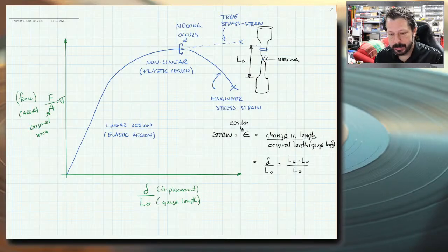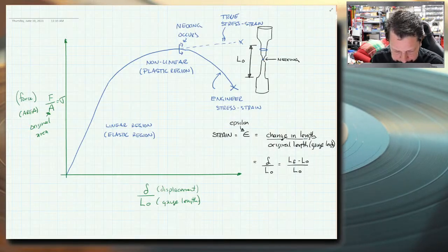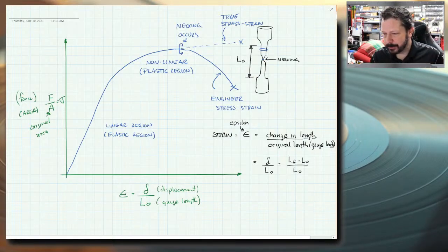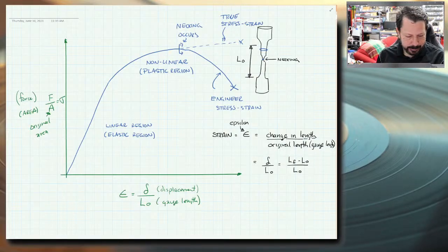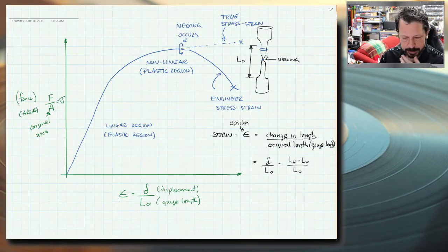That's a good question. So the reduced length is everything outside the threads, more or less, where the fillet begins. And the gauge length, the one that we're interested in for calculating our equation here, is between the fillets. So it doesn't include the fillet. That also tells me that y'all are at least able to see this thing, so that's good. I'm having to run off of a hotspot, so I don't know how stable that'll be. We'll see. So far, I guess it's okay.